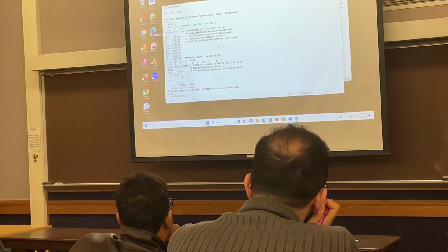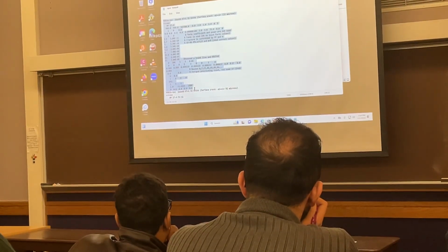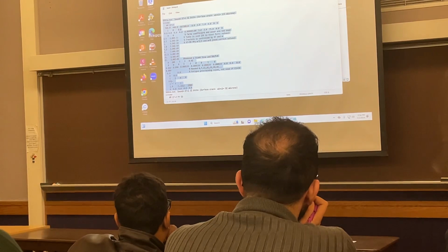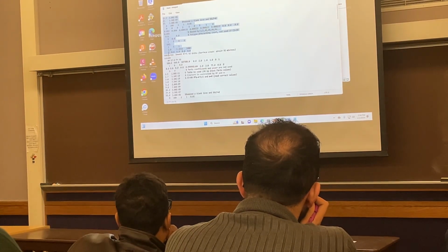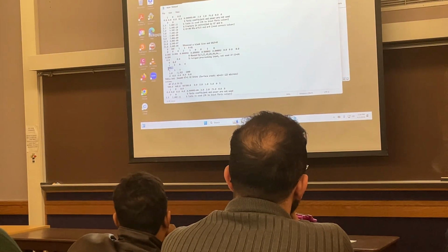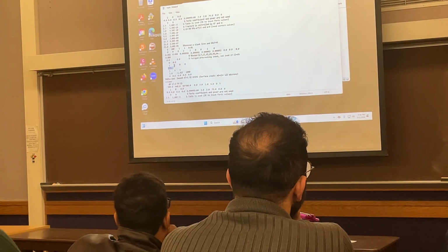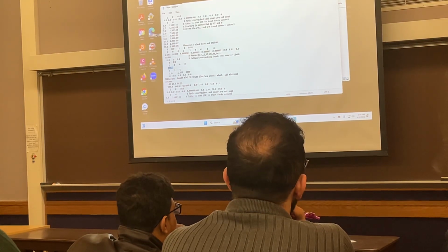So if I open this input file, you see A starts from here to here for this stress level. But after that, you can create another one, for example B, which is just a copy paste of the same thing, but I use a different stress level. So you can put all of this calculation, for example for 8 stress levels, in a single input file, and basically the code solves it right after each other and gives you all the number of cycles to failure.